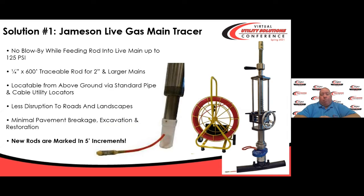Like the example earlier from main goes under the street. You don't have to dig under the street to find it. You can run this cable from an easily accessible point, follow your locate and confirm it because your tracer wire is inside the pipe. So you know you're getting your line.